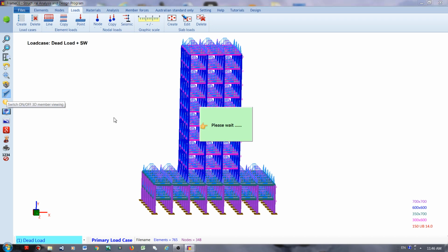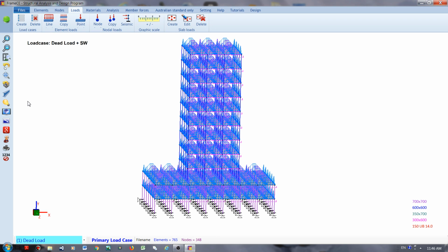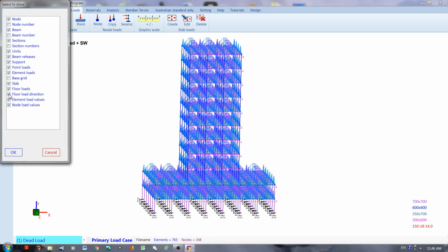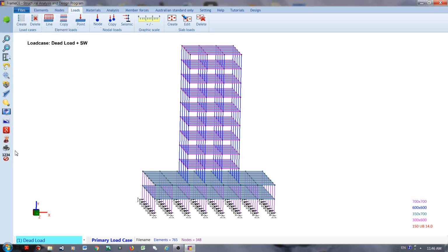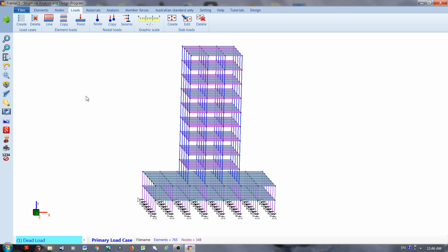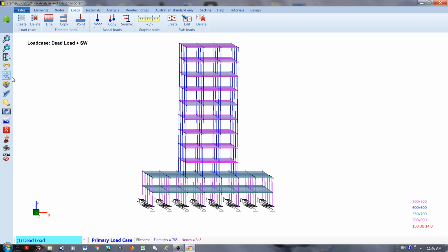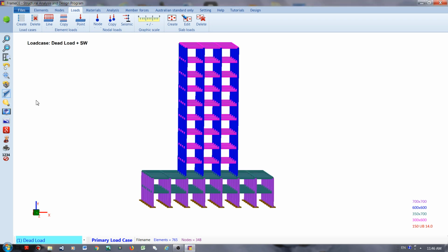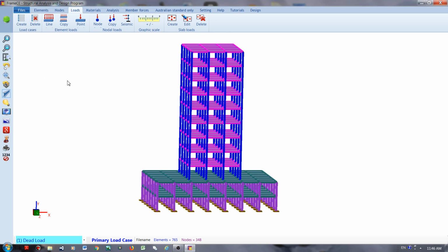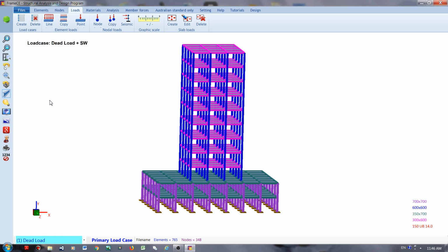So I now have the slab loads and the members of the frame declared. Now you can see here all the floor levels have slabs and slab loads. Now I can proceed with the design or adding more loads to the framing system.